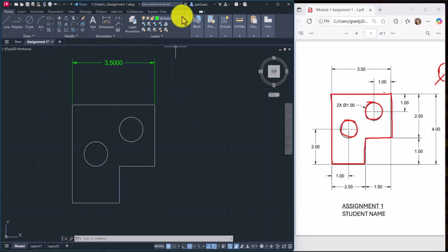Now what you'll also notice is a new layer was created by AutoCAD. It's called def points. It's something that we just want to leave alone because the definition points of this dimension are 2 little dots that are underneath the object at these corners, and they won't plot. That's why they're on their own layer. So we're going to stay away from the layer 0, and we're going to stay away from the layer def points. Those 2 are automatically there from placing a dimension and part of the AutoCAD system.